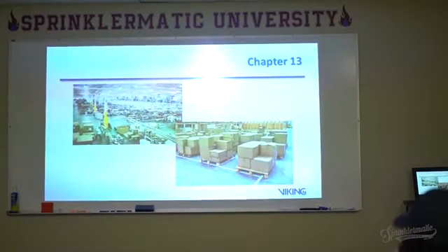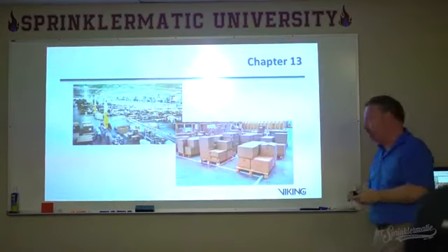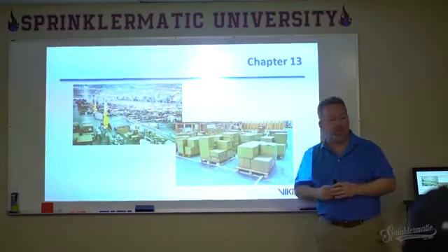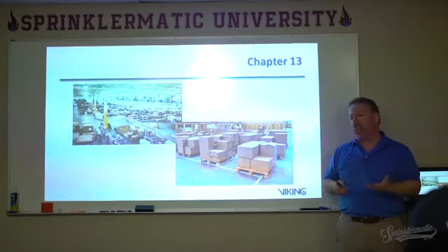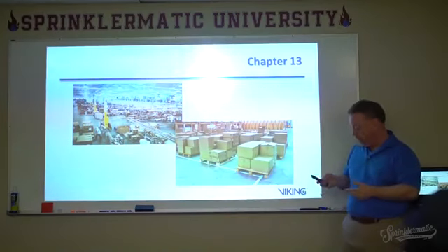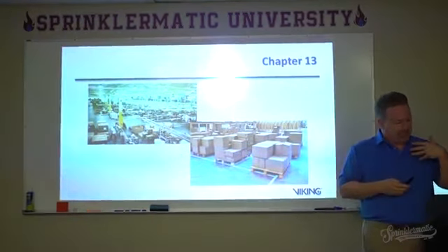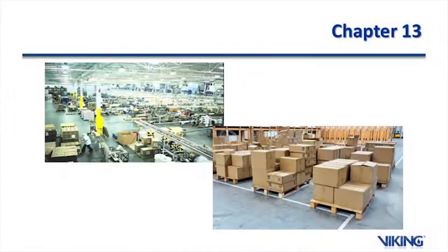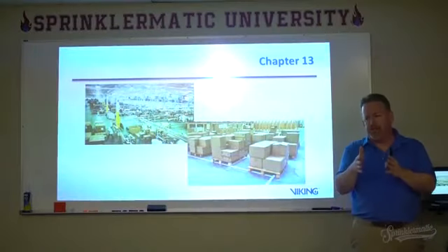All right, so after chapter 12, you come into chapter 13, which deals with what we call miscellaneous or low pile storage. So in NFPA 13, what you have is the occupancy hazard classifications: light hazard, ordinary hazard group 1, ordinary hazard group 2.